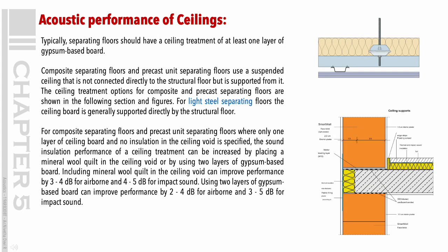Acoustic performance of ceilings. Typically, separating floors should have a ceiling treatment of at least 1 layer of gypsum-based board.